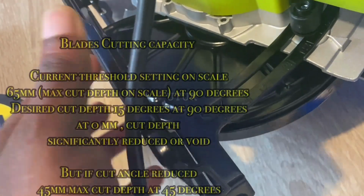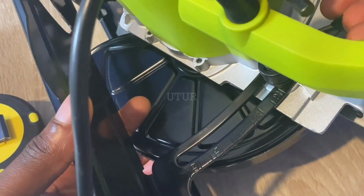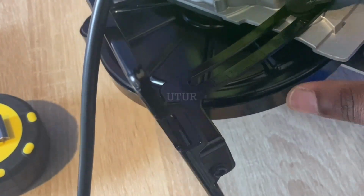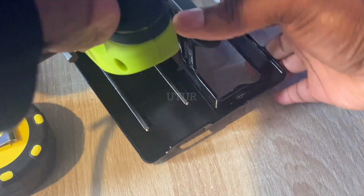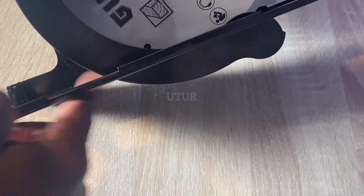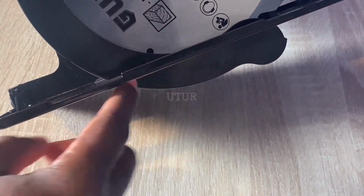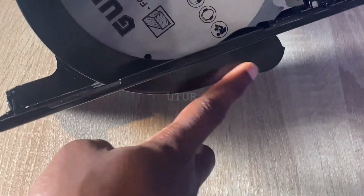And so the cutting capacity for the blade at 90 degrees is 65mm, and if you set the cutting angle to 45 degrees, it can only cut up to 45mm. Suffice to say, if you set the depth of cut to 65mm on the scale, it would provide a cutting capacity clearance of 65mm below the base plate at 90 degrees. 45mm on the scale will yield a cutting capacity clearance of 45mm below the base plate, and at 0mm the cutting capacity below the base plate is significantly reduced.